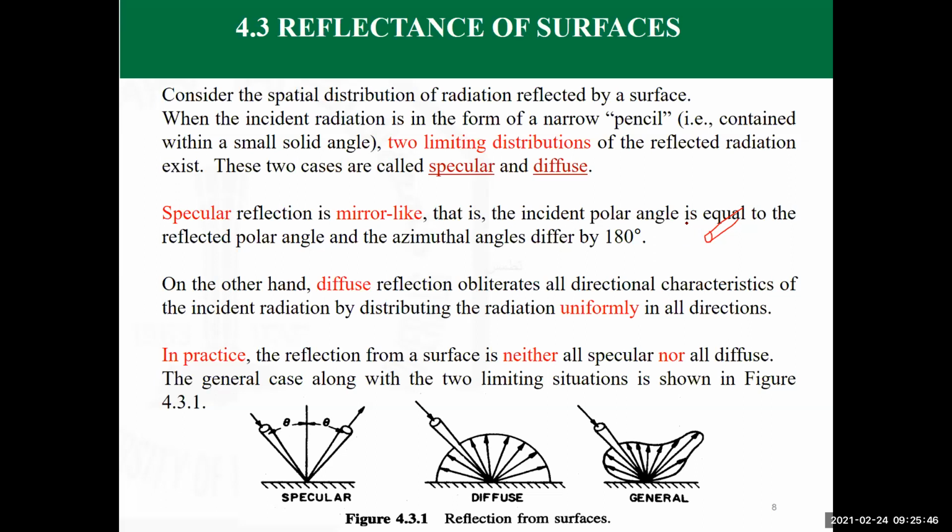So to concentrate the solar energy, you use a parabolic trough so that all the energy falling parallel onto this parabolic surface is going to be reflected here at the focal point. So the property that we are interested in for this parabolic surface is that it should have a high ability to reflect most of the energy that falls on it. You don't need it to absorb energy. I'm not interested in heating this plate. This plate is not important to me. I don't need to heat it, but I need to heat this fluid here in this tube.